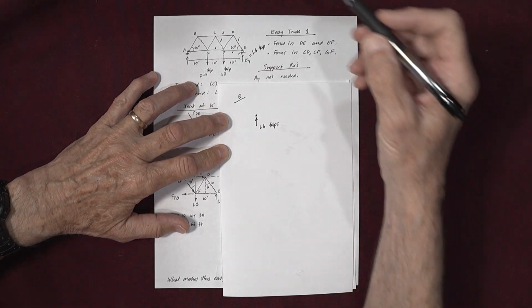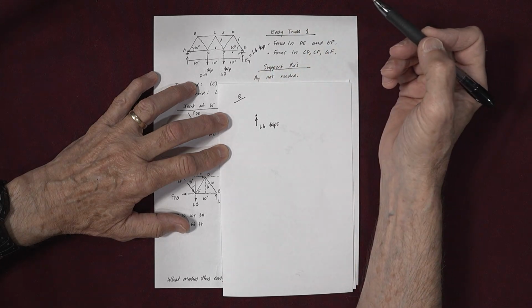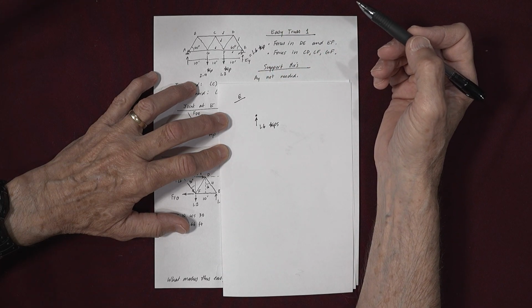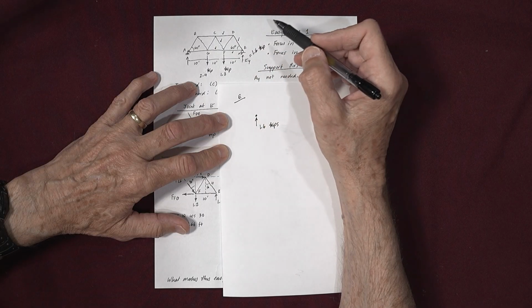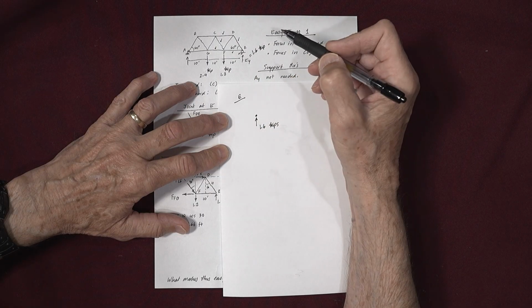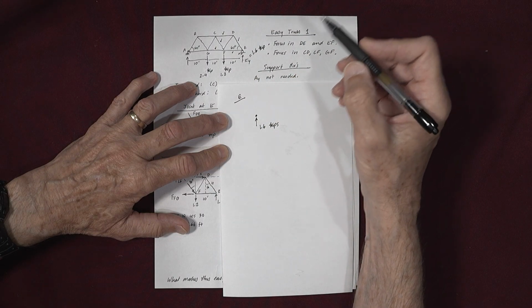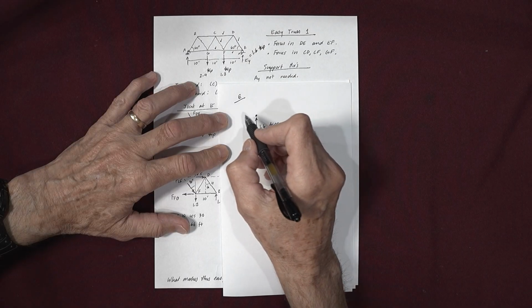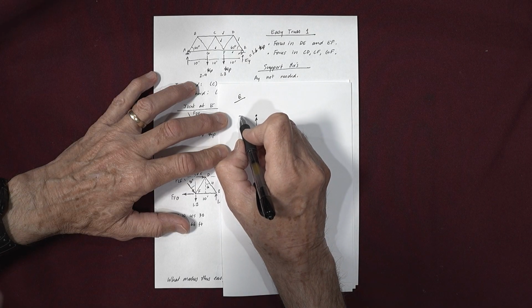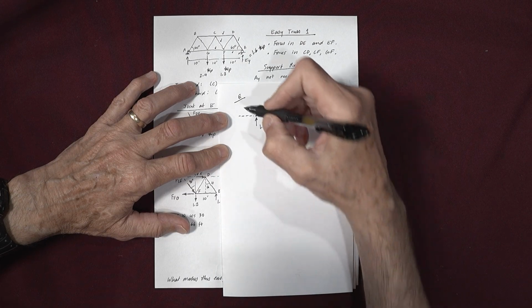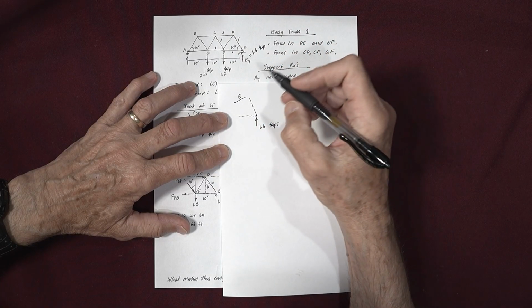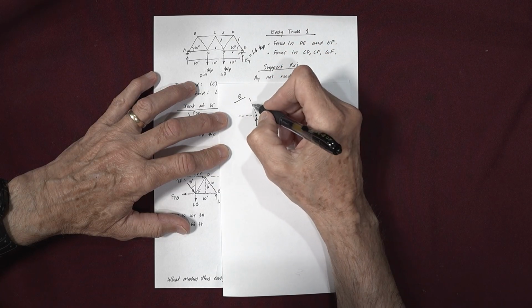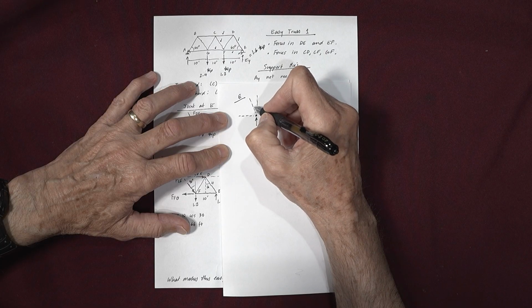So remember, on a truss, all of the members are two-force members. So in other words, the forces are going to act along these members, either in tension or compression. And so when I draw a joint like this, what I'll do is draw a dashed line and a dashed line. And these two lines give me the direction. Of course, this line is 30 degrees.